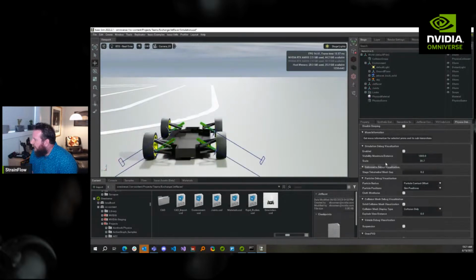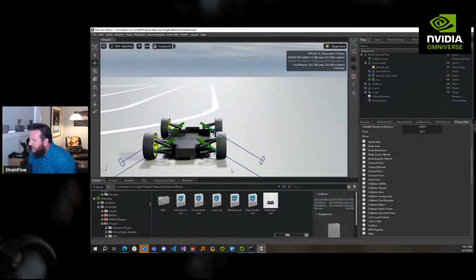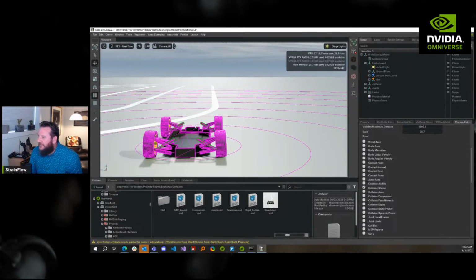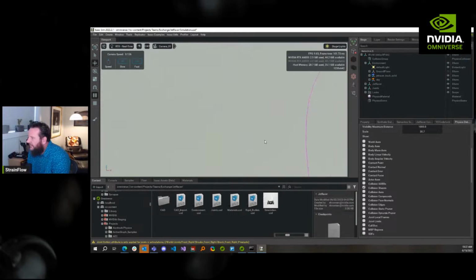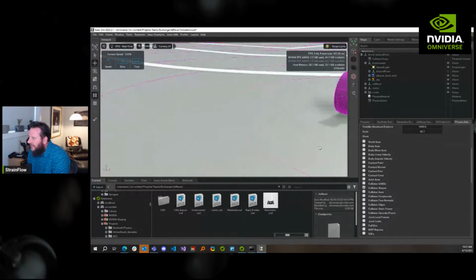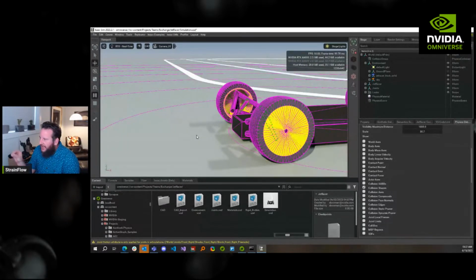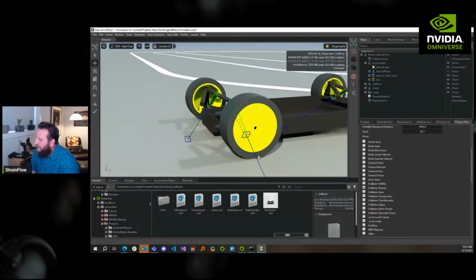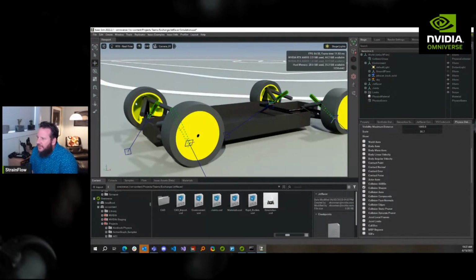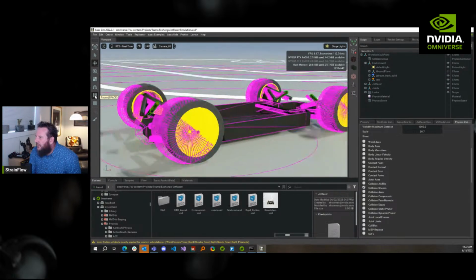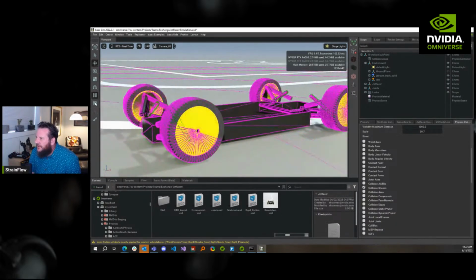No, I want this one though, because it lets you do lots of stuff. We want the collision shapes. Then when we run, you're going to see all of our colliders. Let's look at this collider here. And I wonder if, because it's a mesh and it's not exactly smooth, that's part of the problem. Because it's like the tires start to spin, and then they bounce, you know?